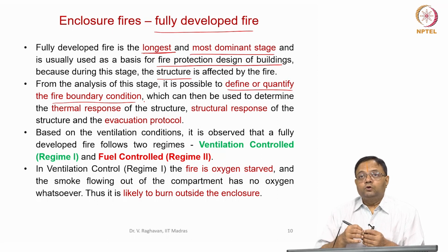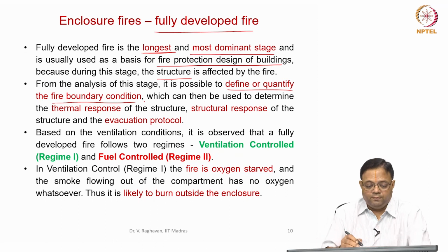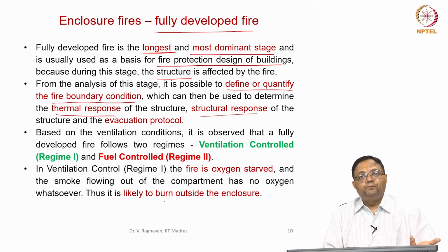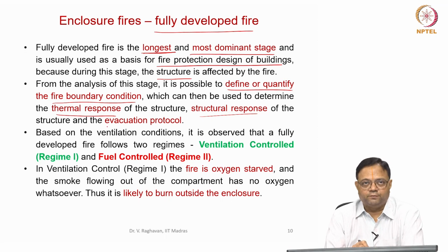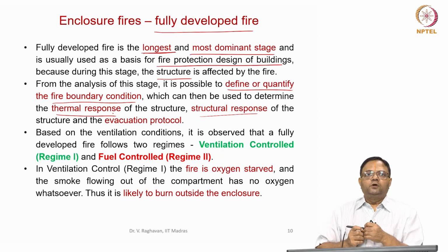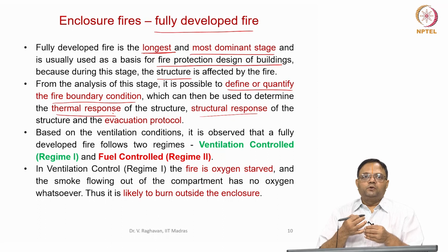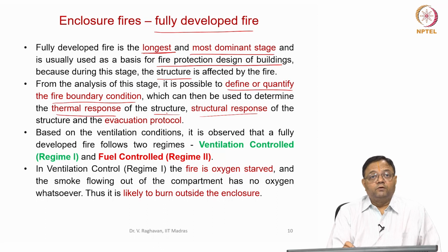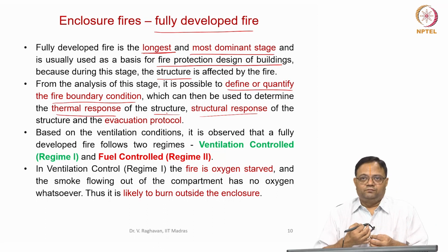Okay, then the temperature increase in the room will be such that the thermal response of the structure or structural response of the structure will be affected or not. So, let us understand the thermal response of the structure. Thermal response is, if there is a structure at say ambient temperature 30 degrees centigrade, it has some strength, toughness, etc. Now, when the structure is heated up, its strength decreases. So, thermal response of the structure is, if the structure is heated up, how the strength decreases.